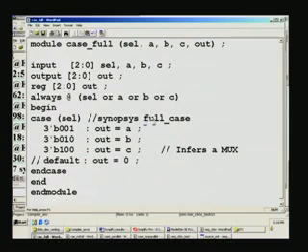So, what is the specific advantage in having this? We will be having a look, right. And what this code is supposed to do is simply assign A, B or C to out, depending upon the select pins. For example, if it is 001, we have seen this for a one hot machine. In one hot machine there will be only one entry 1, and you can see 001, only one entry, one here.